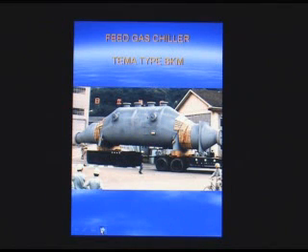This unit used a proprietary tube made by Union Carbide, called a high flux tube, that basically promoted nucleate boiling, so that it had a coating on the tube to promote localized boiling points to enhance the cooling of the gas by boiling up the propane liquid. This unit was built in Korea. Pardon me. This unit was built in Japan.